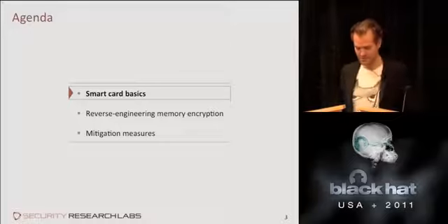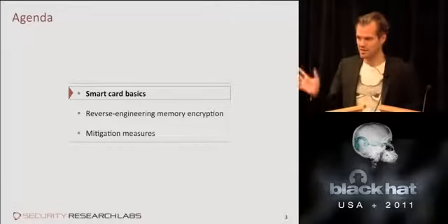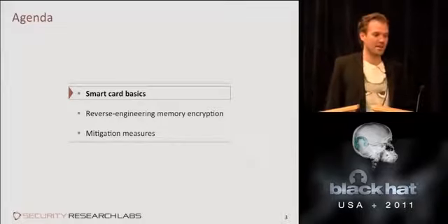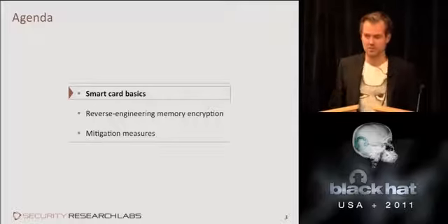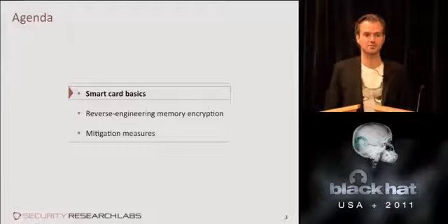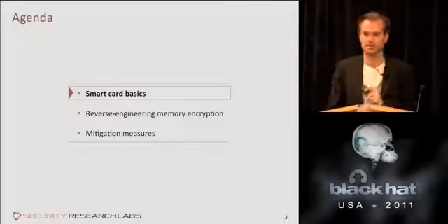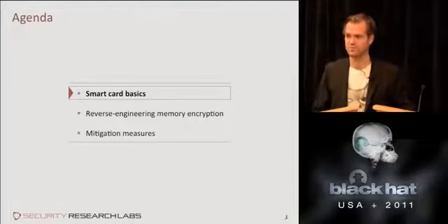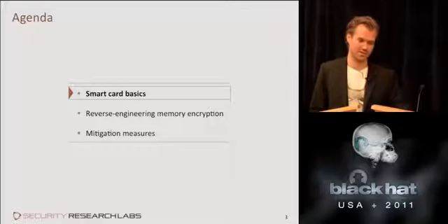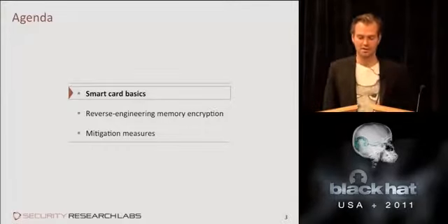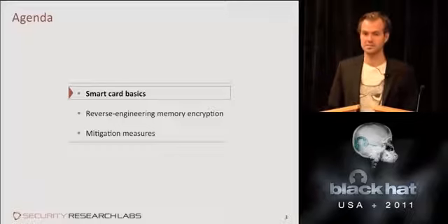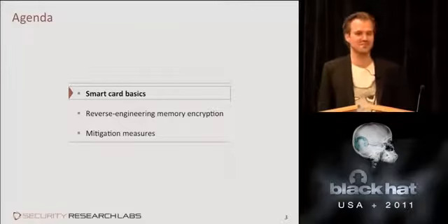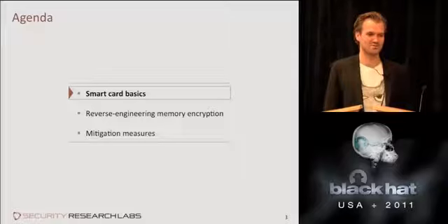we'll start off with some background on smart card architectures. Some of you may never have seen or gotten explained a smart card chip. We'll then show how we, from one of these chips, reverse engineer the crucial function that now allows this extraction of code pretty easily. This one just stands as an example for a problem that will be found in every smart card chip out there pretty much, though. And we'll eventually cover some mitigation measures smart card manufacturers could do to prevent this. However, before they do this, I hope you will spend years of extracting lots of code for analysis.